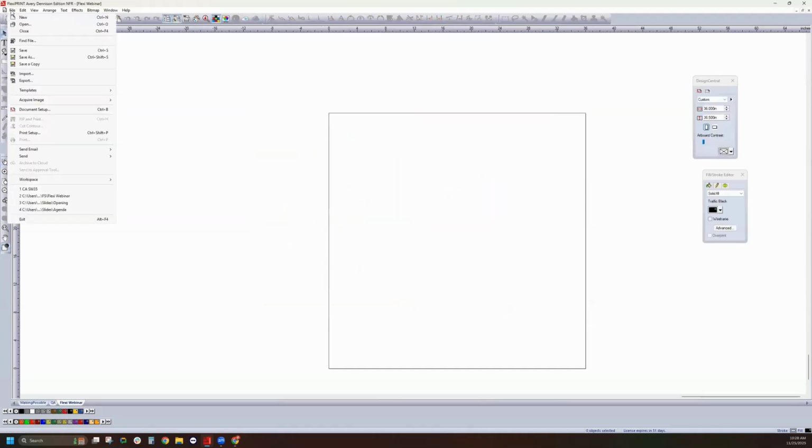So I'm going to bring in a raster example at this point. One thing I'll point out here is you'll notice that I'm going to File and Import rather than File and Open on my files when I bring them in. The reason I'm doing that, it's kind of a best practice. You don't necessarily have to do it, but if you're bringing in, especially a file from a network drive, if you just click File and Open, the software is accessing that file while you're manipulating it.